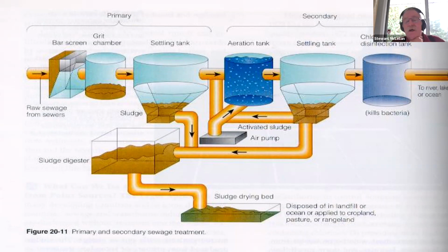So this is a big part of the reason why we have municipal sewer use discharge bylaws, so that they can regulate the amount of heavy metals that are coming into their wastewater treatment plants, because prior to disposing of the sludge to croplands, the sludge must pass chemical testing and must contain low levels of heavy metals.